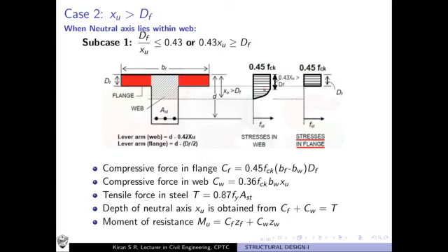The first case being, you see this figure, you have this T-beam given and the depth of neutral axis is greater than the depth of flange, or the neutral axis is lying inside the web. Okay, so what you are going to do, just cut it off here and here, and you get this rectangular beam, and this remaining flange portion also you have, and you are going to draw the stress distribution at limit state separately for this rectangular region, and separately for the flange region.